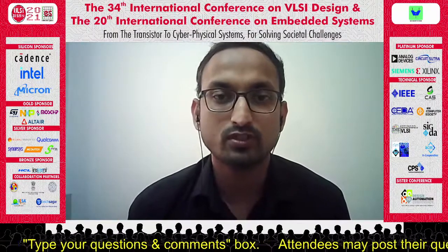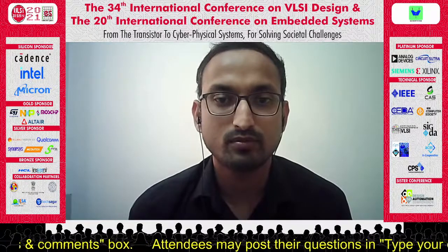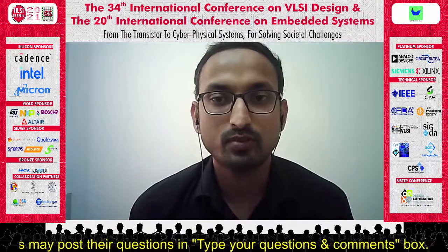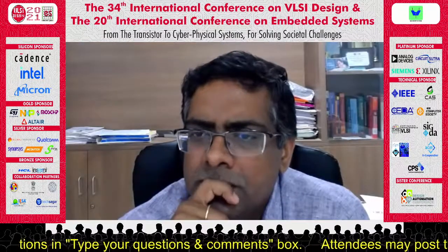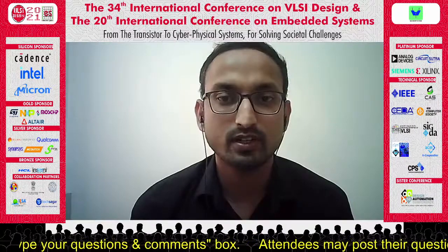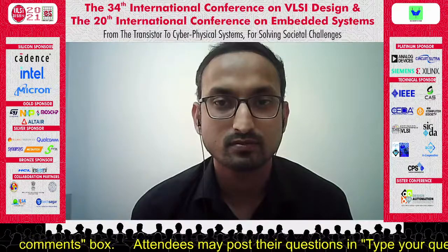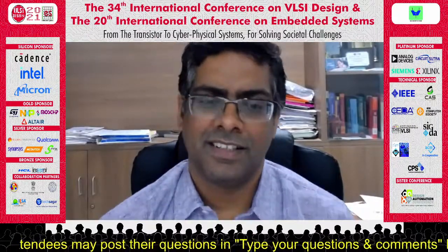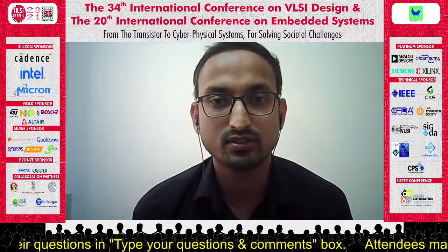Moreover, we have also one solution, the ZTC point, but that is also not feasible because if we want to change our bias point, then this will not be good. So it is better to compensate the gain. We can increase the power supply. So my point was, have you thought of a circuit which will dynamically change the power supply based on the self-heating rate? Yes, sir. In future work, we can do that. I think a feedback circuit can be used.